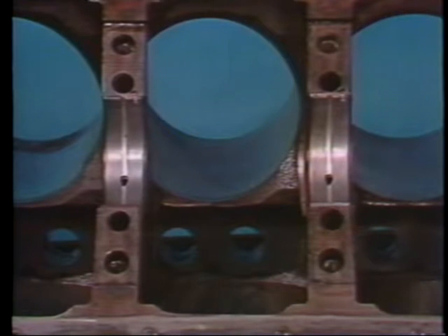These bearings must be installed in the upper half of the block, so the holes in the block line up with the holes in the bearings. Therefore, the bearings shown are the upper crankshaft bearings. The correct answer is response A, for A only.